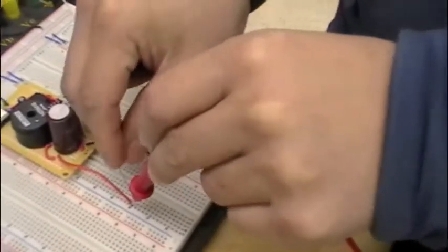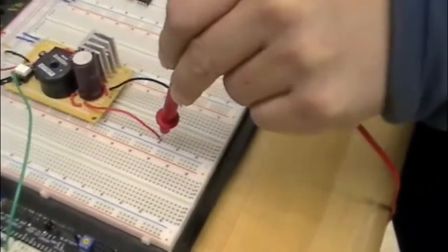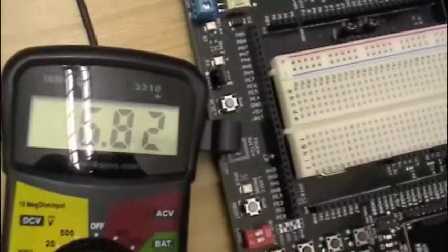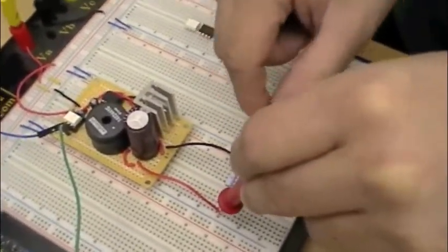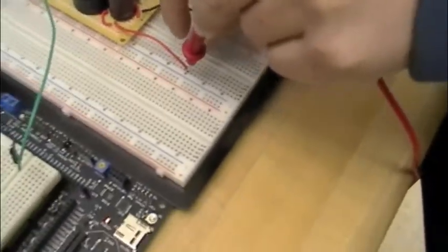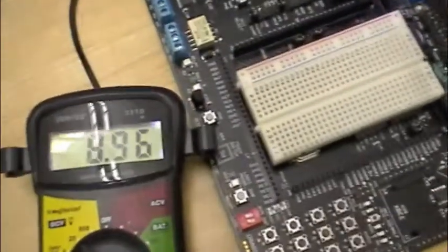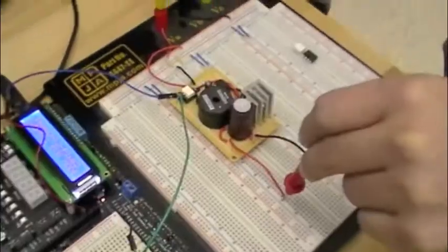And then when we apply our load, this is the load that's going to deliver the maximum power consumption, 4.5 watts. And as you can see here, our output voltage is 6.82 volts. It sags because we have a lot more current being drawn through the circuit, and those losses are reflected in our voltage output. And then once we pull the load out, our circuit settles down to our designed 9 volts.